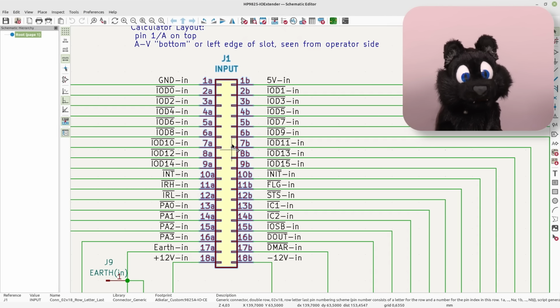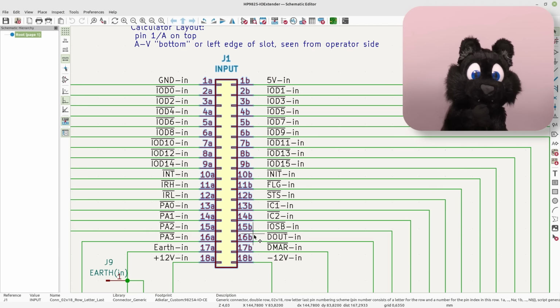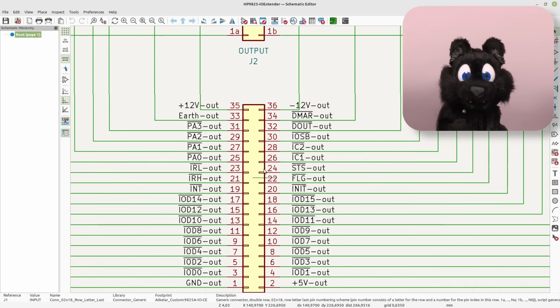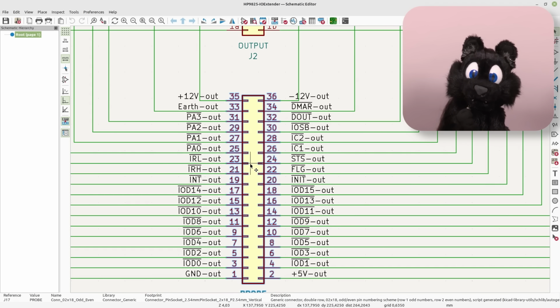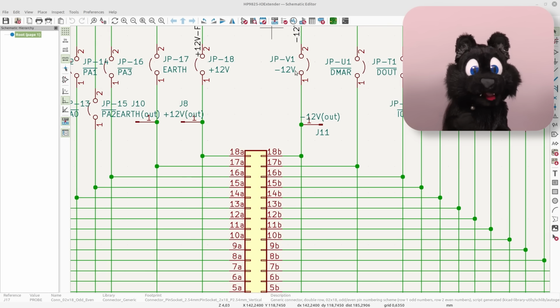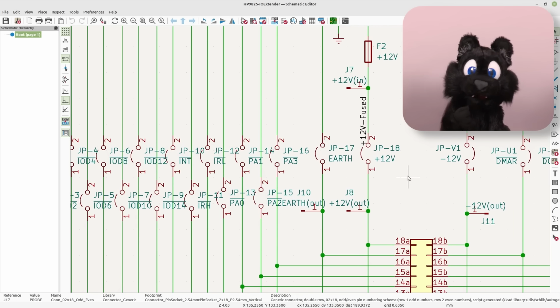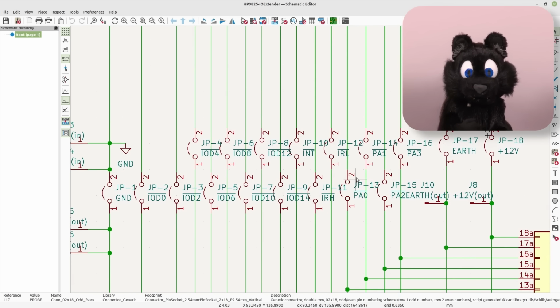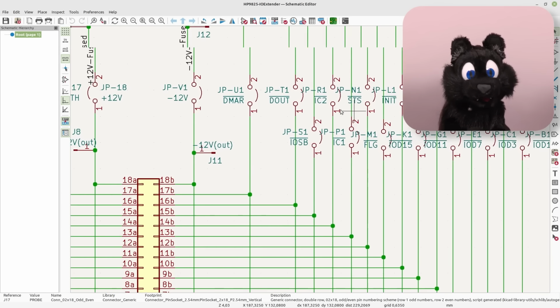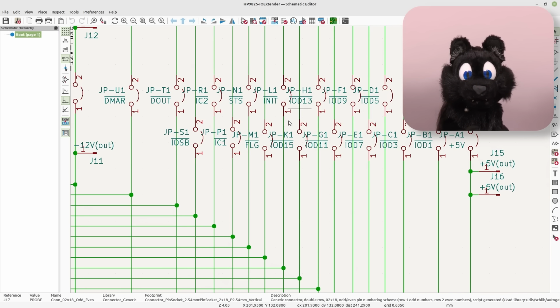Now, just connecting the two card edge connectors in a 1-to-1 scheme seems a bit boring. What features can I add? Oh, how about a pin header too, so I can easier hook up the logic analyzer? Yes. And jumpers to selectively connect or disconnect a signal? Also a useful feature. I could have used dip switches, but the jumpers double as additional connection points for measuring.